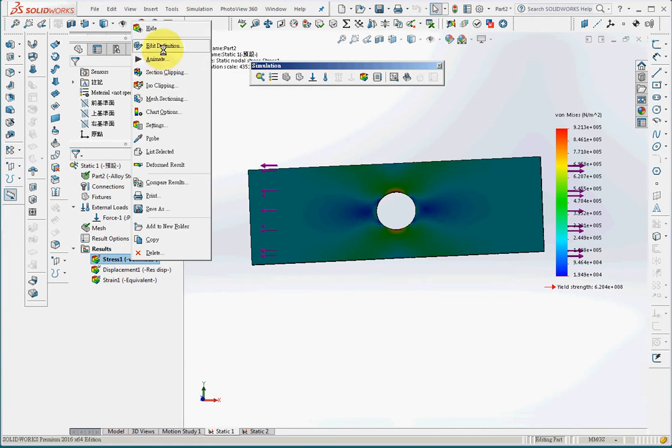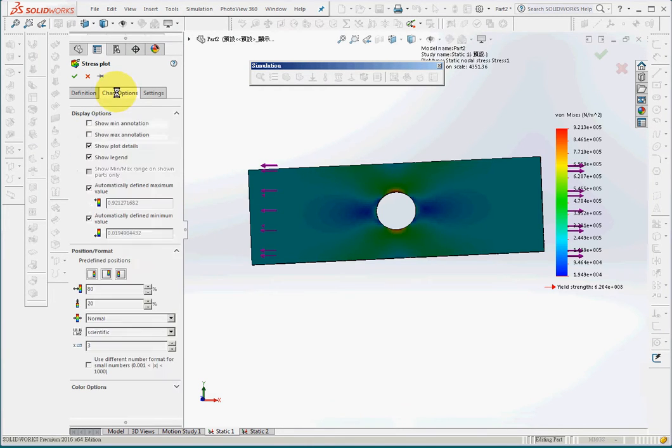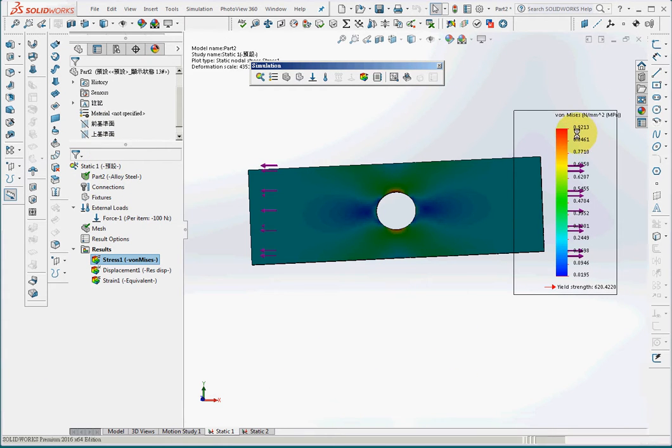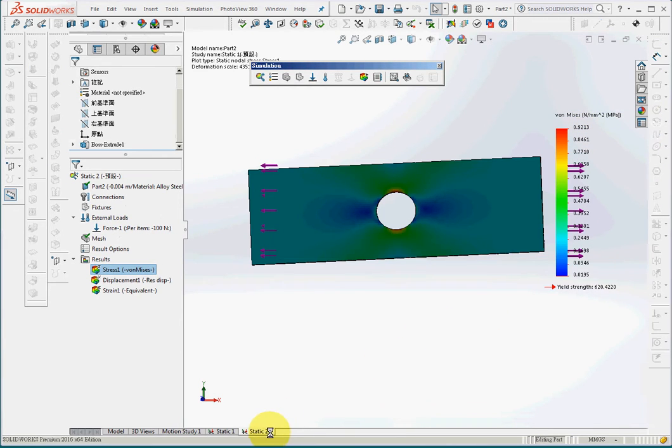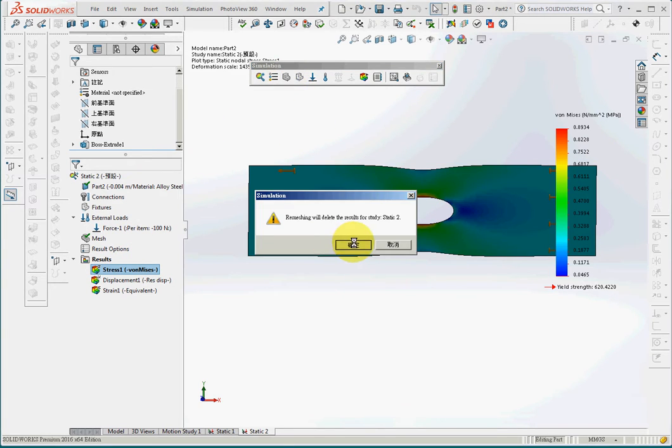I can also change the unit into MPa and the format of the result into floating point with 4 digits on the decimal. So I have 0.29 MPa in the 3D model, and 0.89 in the 2D model. But now I'll mesh it into a finer mesh.